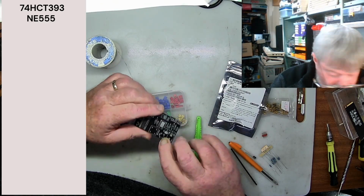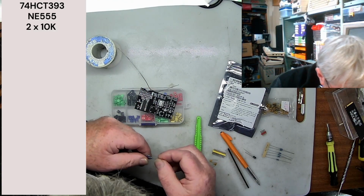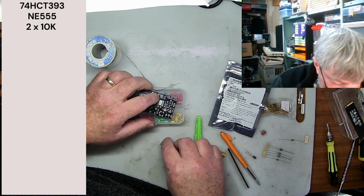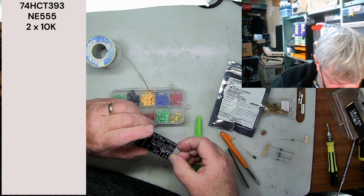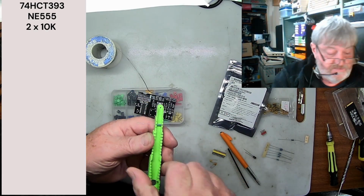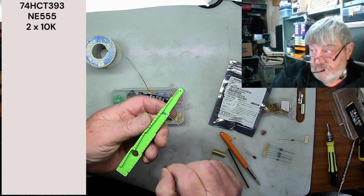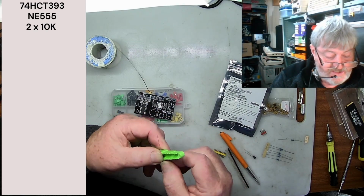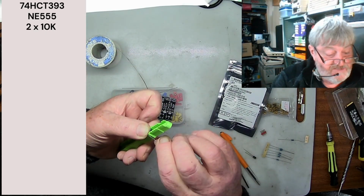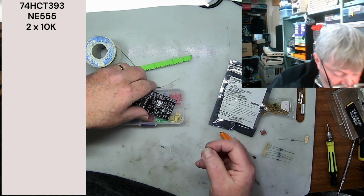So the next thing I'll do is put the resistors in. I've got a couple of 10k's to go in. And these are quite soft legs. And that's what I say, so you take your component and depending on how far apart you want your legs, you just drop it into whichever size it is. So this is about close to the one I need, and then you just fold them down the sides of the leg spacer, and then they pop out, and that gives you nice square legs that then should pop in.